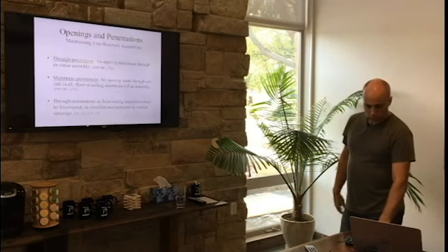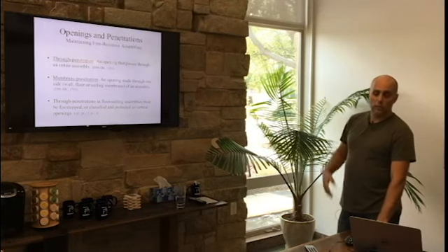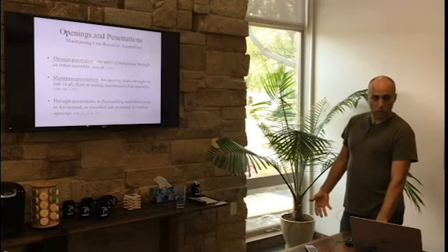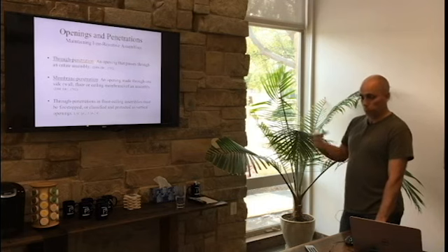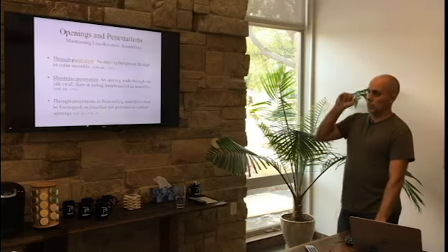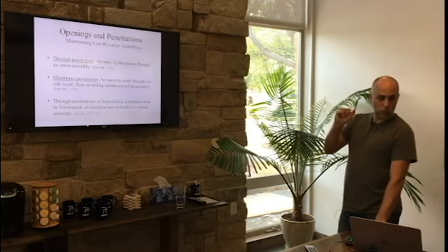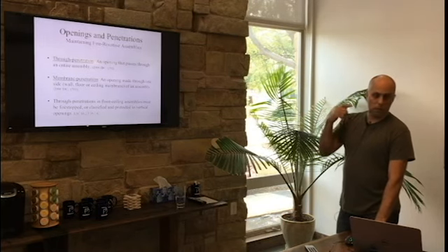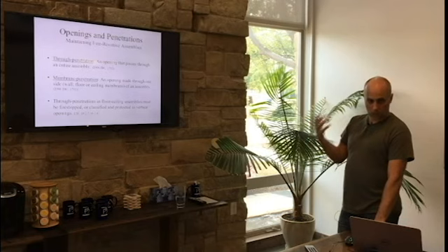Okay, and then I'm not going to get into a lot of detail on the penetrations, but basically, if you put a hole in a rated wall, and it doesn't matter whether it's above or below the ceiling, you've killed the wall. A pinhole in any rated wall will allow smoke to just shoot through. Because when air heats up, you get a higher pressure.